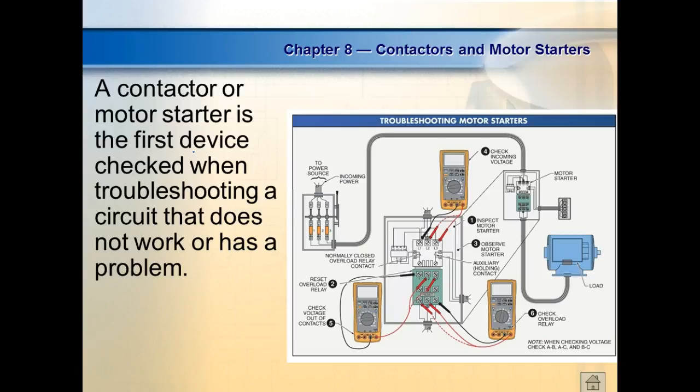And of course, the way we're supposed to mount these things, we're supposed to mount them vertical. You understand? And where does power come in? Top. And the loads are connected on the bottom. And that's true on disconnects and all kinds of stuff.